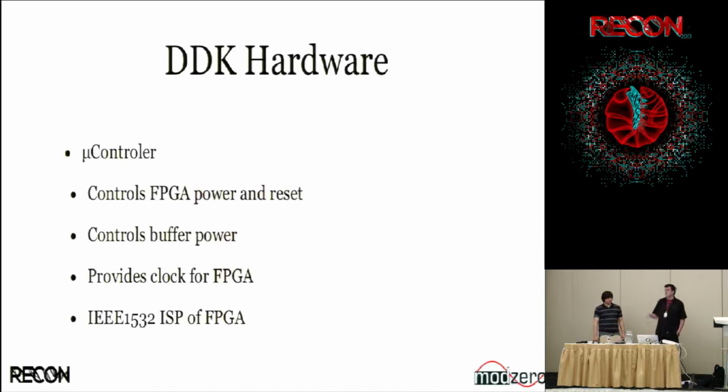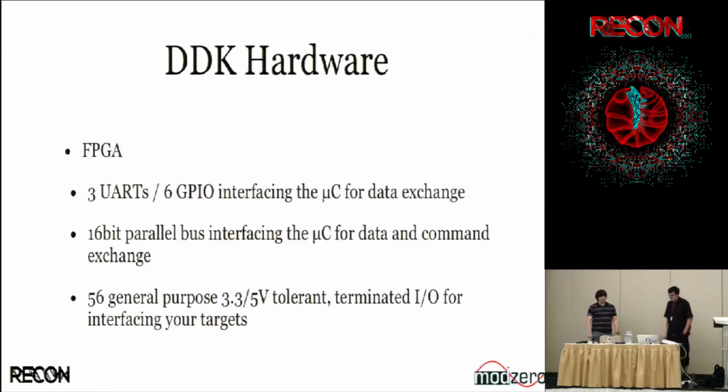Also, we implemented code to flash the bit stream for the FPGA. Fortunately, the microcontroller, as opposed to some cheaper ones, is big enough to store a full FPGA bit stream in the hex file that we distribute on these. So if you ever mess up your Datenkrake, for example by using an external programmer, and you want to go back to start, it's not a problem. You can just erase it and flash it again using the command line interface, which we'll see in a little bit.